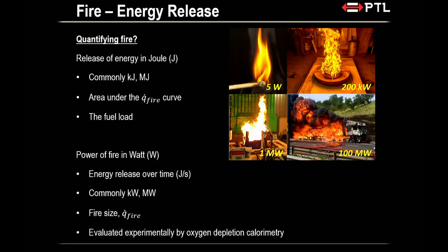Why? Because this picture here gives you the depiction, right? If you have a match, you strike it, light it, that's about 5 watts. That's a no fire, don't worry about that, right? If you have a pool fire, which is about 20 millimetres diameter, a heptane pool fire, you'll get a peak of about 200 kilowatts, all right? That's a bit of a concern, right? Now, if you have a couch sitting inside your living room, for example, if that ignites at its peak, it will generate 1 megawatt, or 1,000 kilowatt. All right, a bit more concern as well.